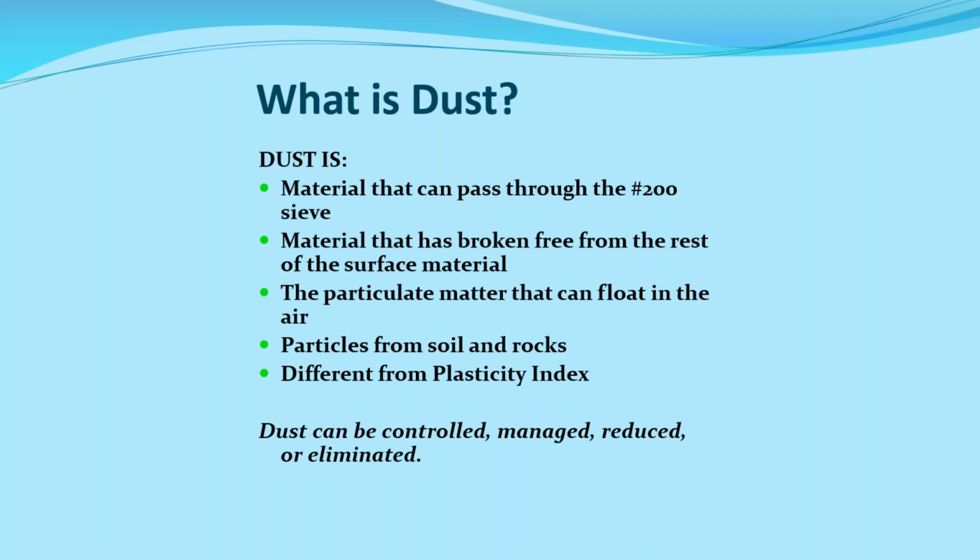But dust is the particles that float in the air as a vehicle travels down that roadway. It can be from the soil, can be from the rocks, and also, depending upon the plasticity index and how well it is holding together and how dry the roadway and the material are, that dust will increase. Or if we came in and graded that roadway as a dry roadway, we broke that crust, we've now fluffed it up and enabled the vehicles to easily blow that material off the roadway, creating a problem for us.